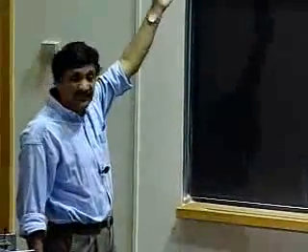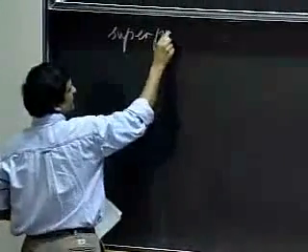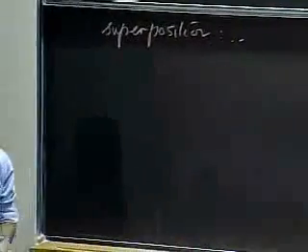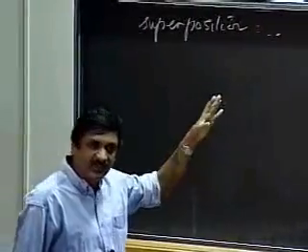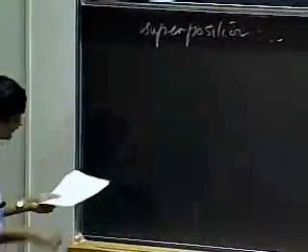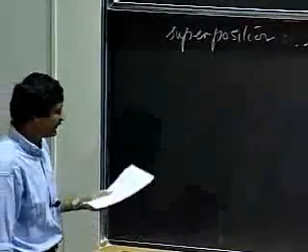The op-amp is simply another building block. It's a linear circuit. So let's use superposition and see if we get the same answer. Let's try to solve the circuit using superposition. To do superposition, what I'm going to do is build two subcircuits.